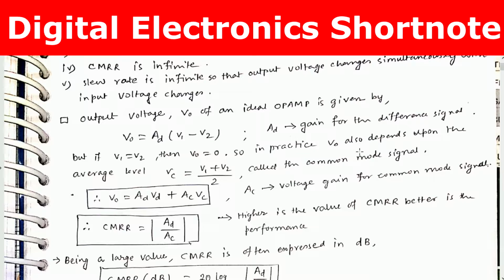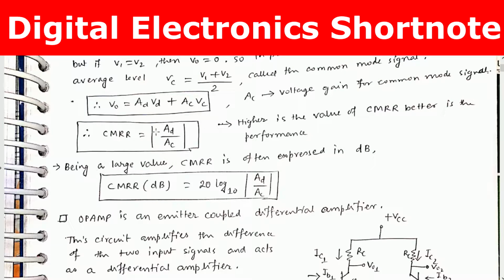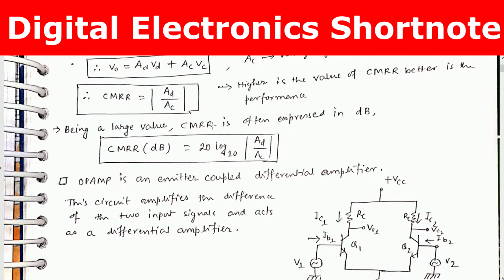So in practice, V0 also depends upon the average level. Vc equals (V1 plus V2) by 2, and this is called the common mode signal. Therefore, the total output voltage in practice is V0 equals AdVd plus AcVc, where AC is the voltage gain for common mode signal. CMRR is given by AD by AC, and a higher value of this CMRR gives better performance. For large values, CMRR is often expressed in decibel, and it is written as 20 log AD by AC with base 10.